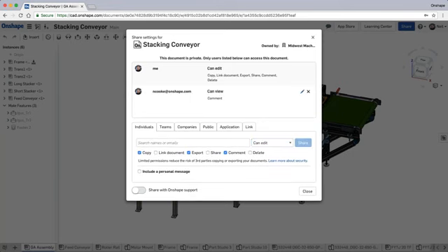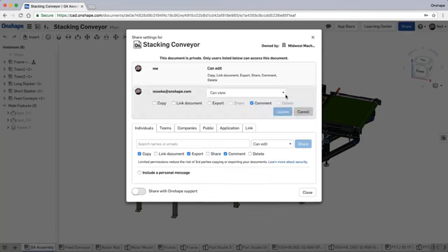Now, once that person has worked on a design or looked at it, made some comments, if it's a supplier, you may want to approve them as a supplier, and then change their editing permissions. Simply by specifying that they can export, for example, means that perhaps they're doing some CAM work on it. They've got to do some machining. So if they're using something like Mastercam, they'll want the file format in something like STEP or Parasolid.